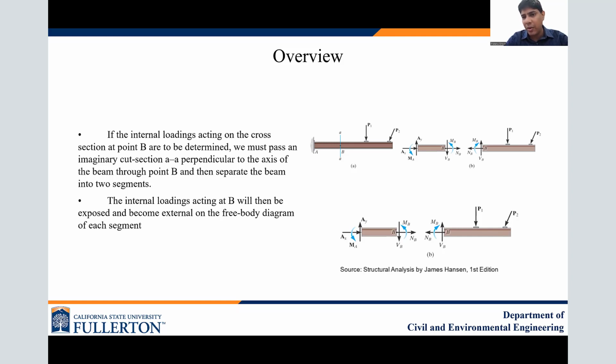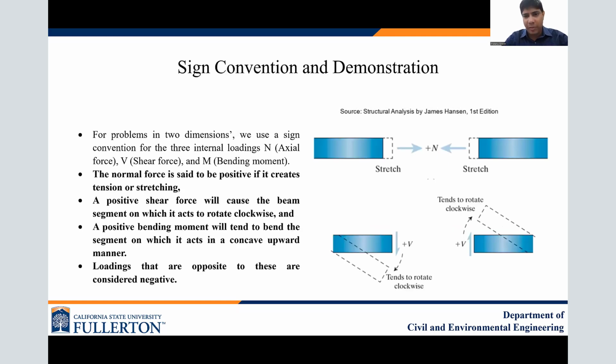So as you see, the sign convention is very important. Either way you can cut it, from left or right. You have to use your judgment. Wherever the side has minimal loading, you should go from that side so that your calculation will be a little bit easier.